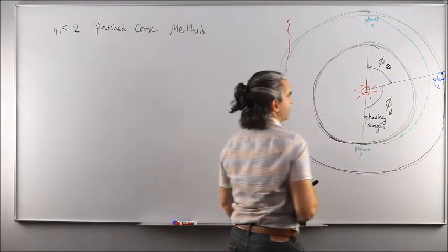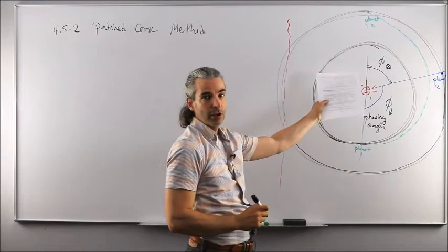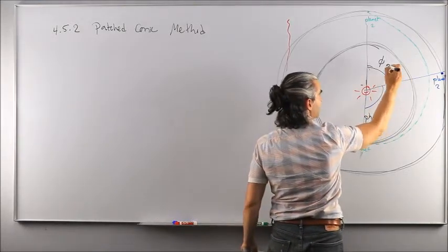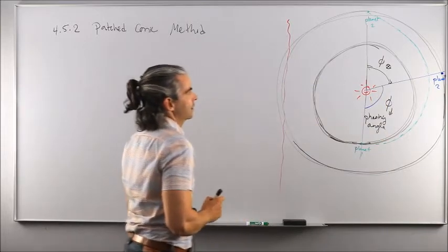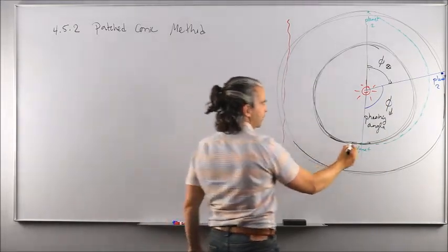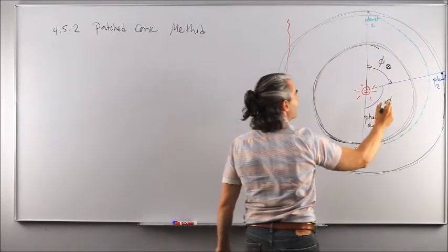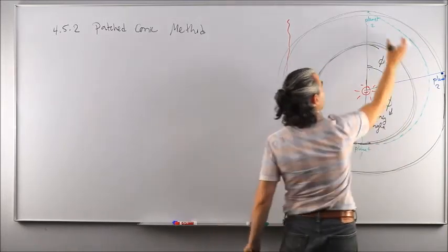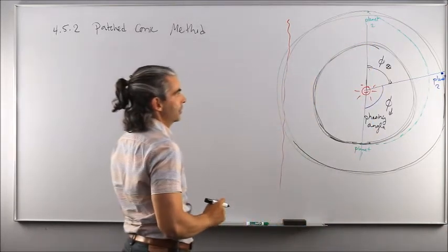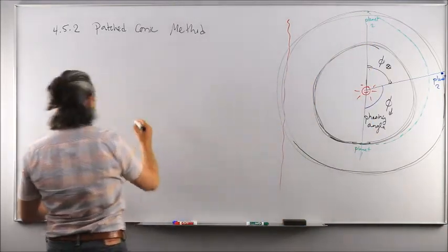We're going to use subscript circle x whenever we talk about the target planet, because that kind of denotes a target, essentially. So this is the target planet in terms of what it needs to cover during the time that the spacecraft spans along this transfer orbit, such that the spacecraft and planet 2 meet up upon arrival at the apogee of the transfer orbit. Okay?